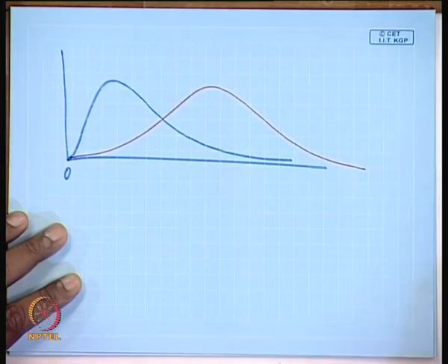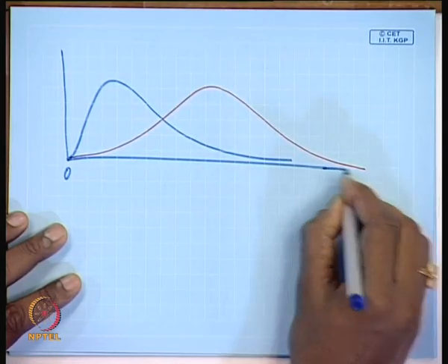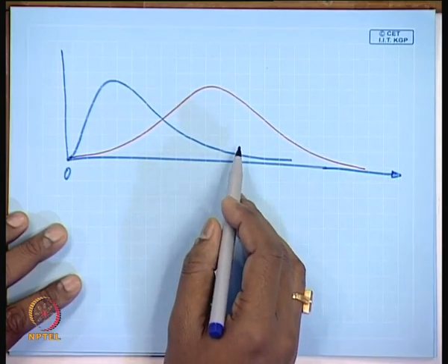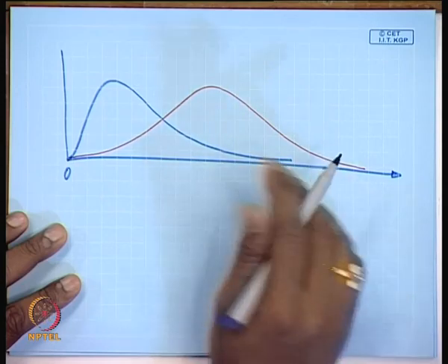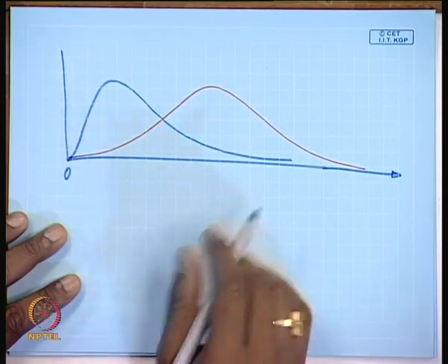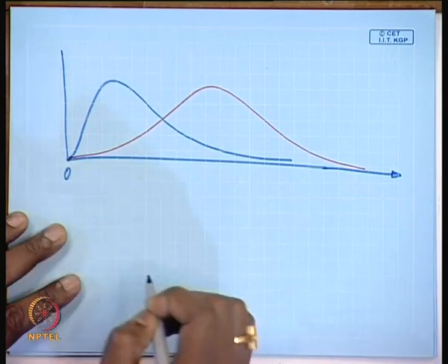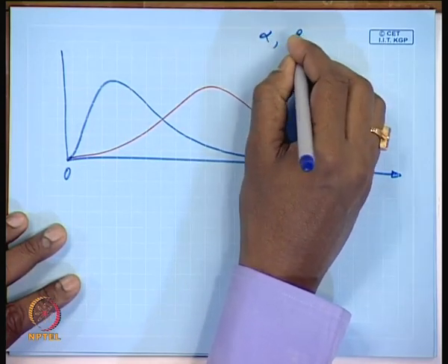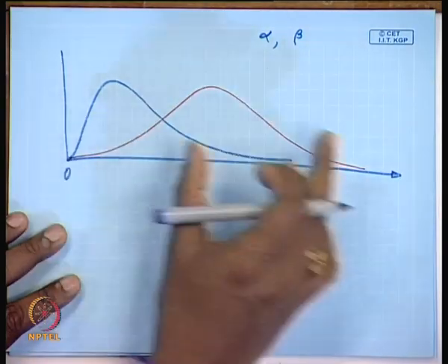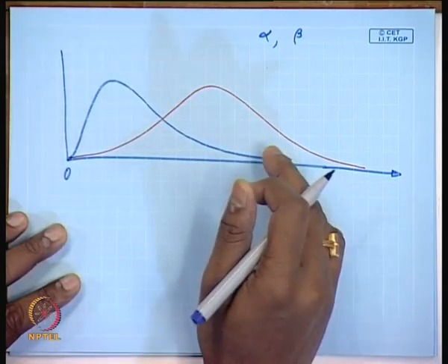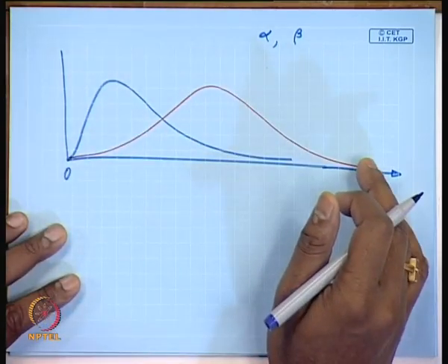Sometimes for very large rivers, the flow has a symmetrical shape, like a normal distribution, but again the lower bound is 0. Just by adjusting these two parameters, alpha and beta, of the gamma distribution, you can control the shape from exponential to positively skewed and even to symmetric.